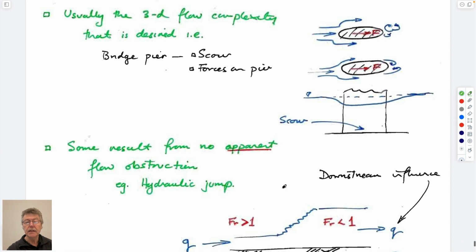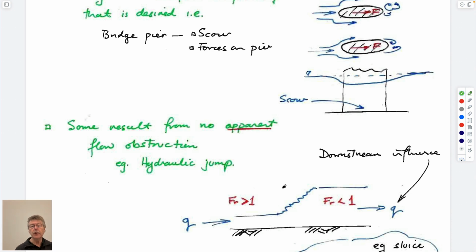And the deal is that if you have flows which are flowing at quite high velocities, so supercritical flows, sometimes they're unstable. So if you do something to it, like have a bump in the bed of the flow, or some small perturbation, all of a sudden it triggers this, I guess kayakers would call it a pile up of water, that it slows down to subcritical flows, and as a result backs up, so that when you talk about dy/dx approximately 1, that's saying that this slope here is exactly what this is.